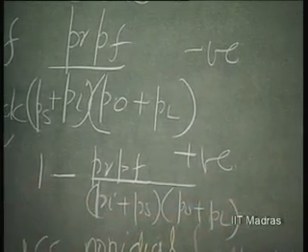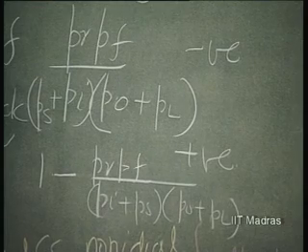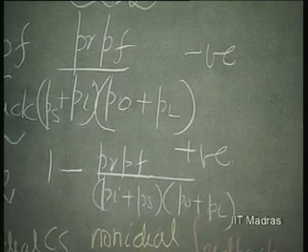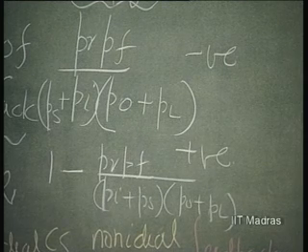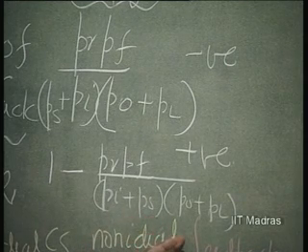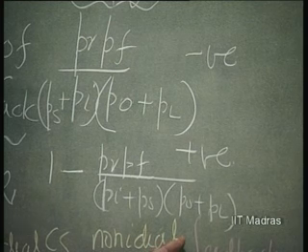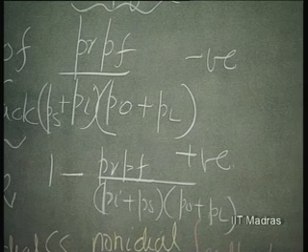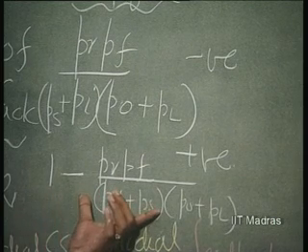The factor by which things improve: if things are in shunt at the input, the admittance level goes down by a factor determined by this. If things are in shunt at the output, again the admittance increases, the impedance level goes down by a factor determined by this.